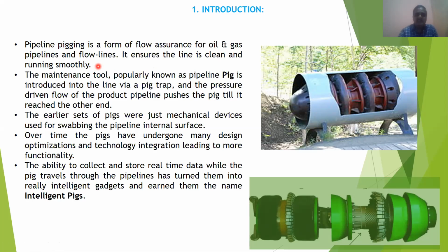Normally, during construction or during operations, there is a lot of debris. Many things will be there: rust formation, scale formation during operations. To prevent those things, pigging is important to ensure that all flow lines are clean and running smoothly.